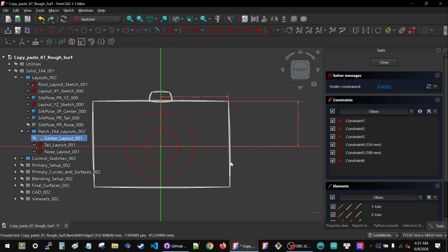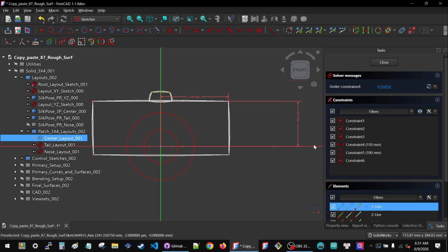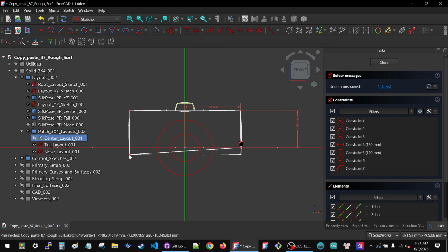And the way I do that is by moving these lines so they don't cross over the points of my 3-point sketch. So I'm pretty close to the x-axis. Right now I can do it. Grab this point, the x-axis, coincident. Then this point, the y-axis, symmetric. Okay, and my sketches haven't gone crazy yet.